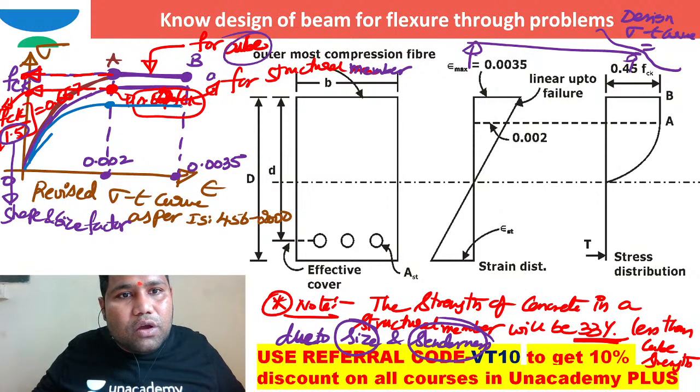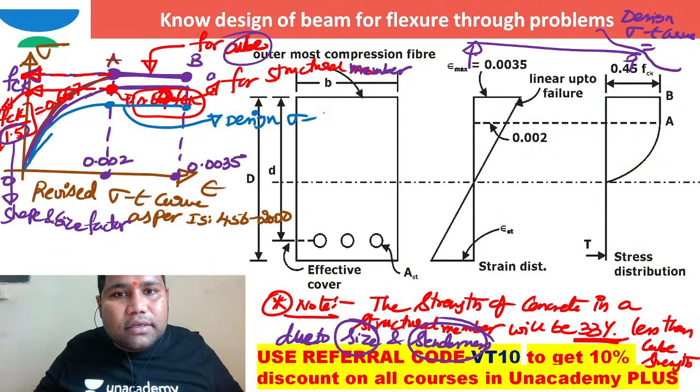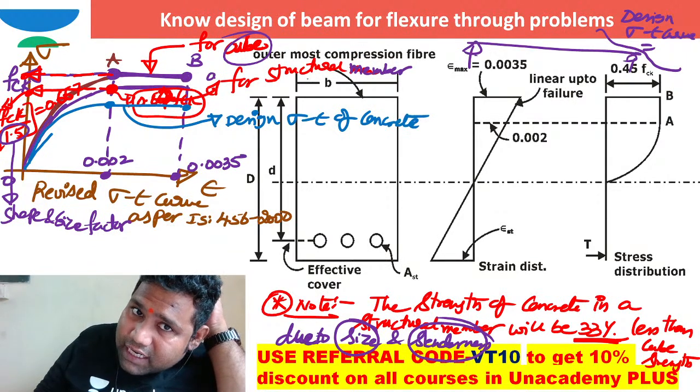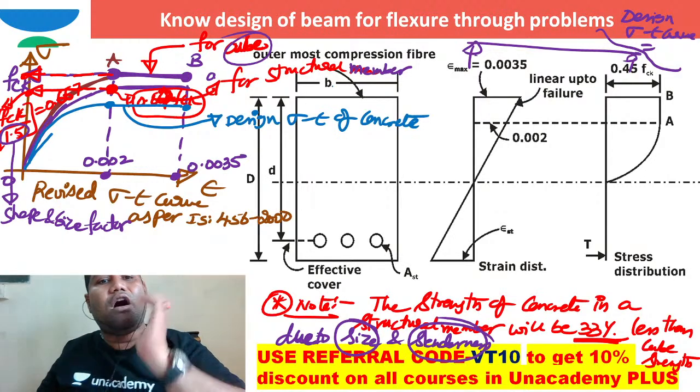What is this blue one? This blue one is called a design stress strain curve, the design stress strain curve of concrete. So how will you get the design stress strain curve of concrete? The idealized stress strain curve for the structural member of concrete is divided by the factor of safety of concrete.